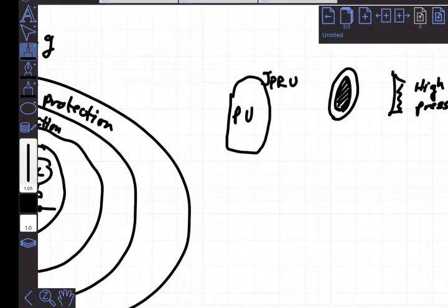Right, so that bursting disc has now ruptured. So as pressure goes up in this vessel, that little valve on the side is typically mounted in such a way that it can be replaced if it bursts, so that you don't have to throw away the whole vessel. And so that means we've got a mechanical safety device.